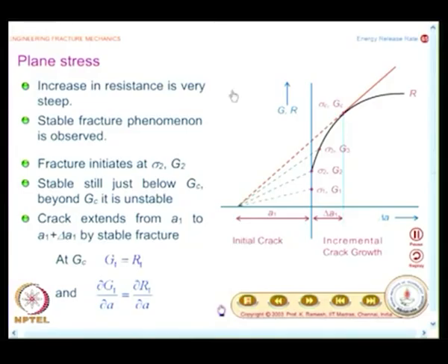After doing that, you find you are able to develop the concept of R curve, which provided explanations for difficult phenomena. So, look at in this graph, I have an original crack A1 which had two phases. There is a stable crack growth phase delta A1. That means what? If I increase from sigma 2 to sigma 3 to sigma c, until I reach sigma c, the crack would not become catastrophic.